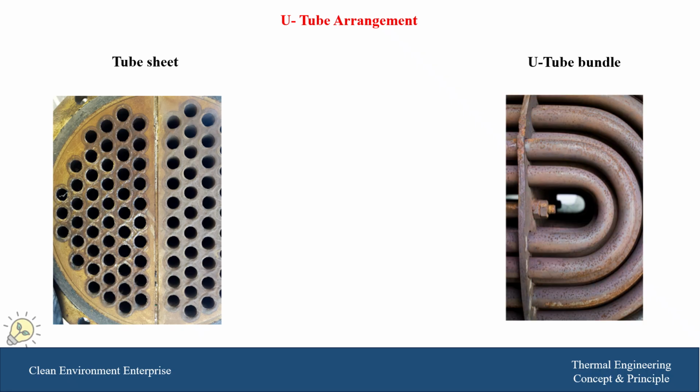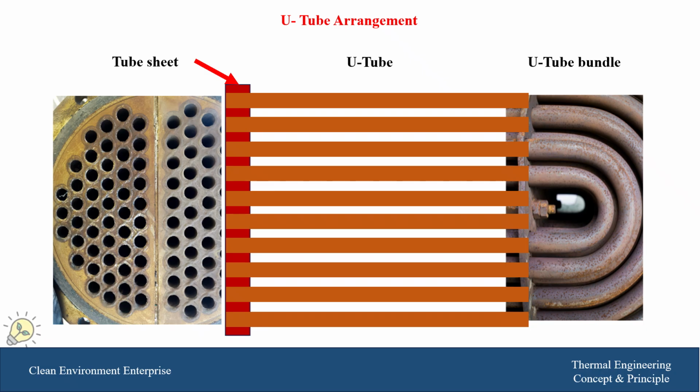And on the right hand side, we have the other end of these tubes in the form of a U. And the tubes are fitted in the tube sheet as shown in this middle part, and the fluid passes through these tubes to the end and returns in a U shape to the same end of the tube sheet.